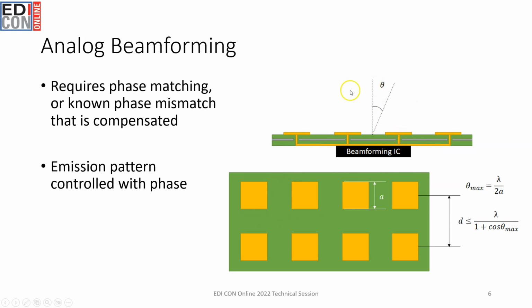And that tilt can be done actually in two angles, in azimuth and elevation, within this array. So we essentially have a 2D scan here. Usually this is presented or talked about in terms of a 1D scan, or in terms of a single angular scan, but you can actually do this in 2 dimensions. And you can get varying levels of resolution in each dimension.